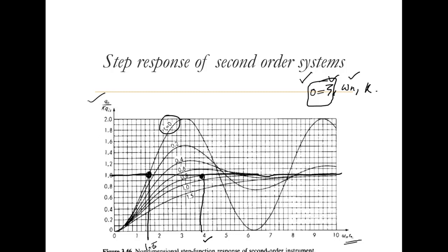So that's why there's a compromise when you design these systems on these parameters, whether you need to increase the stiffness, you need to increase the mass, you need to increase the damping. So all these have to be done together in such a way that you get the best performance. Usually in engineering systems, we use zeta equal to 0.6 to 0.8, more preferably, as the trade-off.